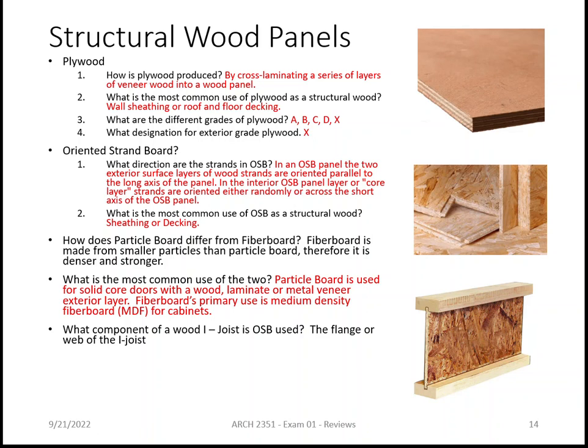In finished plywood, okay, you have what is called A and B. Most finished plywood that's used, and so that outside veneer is usually a high quality wood. Normally a finished wood, which means it's normally hardwood. Hardwood like maple, oak, ash, okay? And it's very clear. A means a very clear piece. B is with some flaws, okay, but minimal. So the most common is an AB for finish.